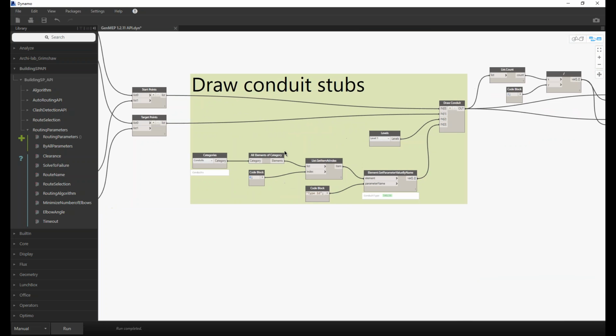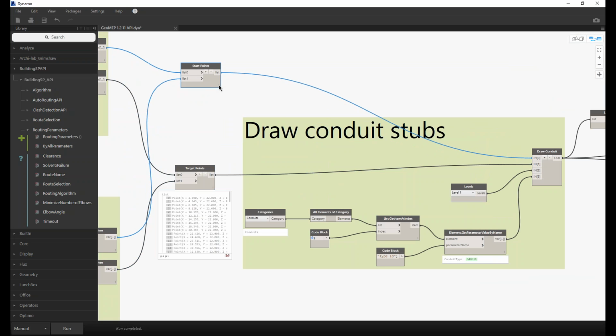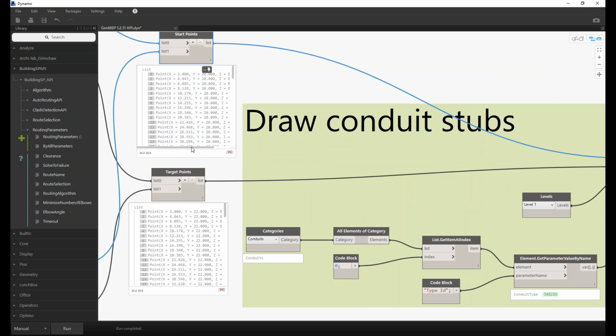So the way you would use this is if you had a pipe, you could ask whether or not it was acceptable to put a hanger at that location in the pipe, and then it would do the check, and if it came back as being clear, you could have Dynamo auto model in the hanger for it.